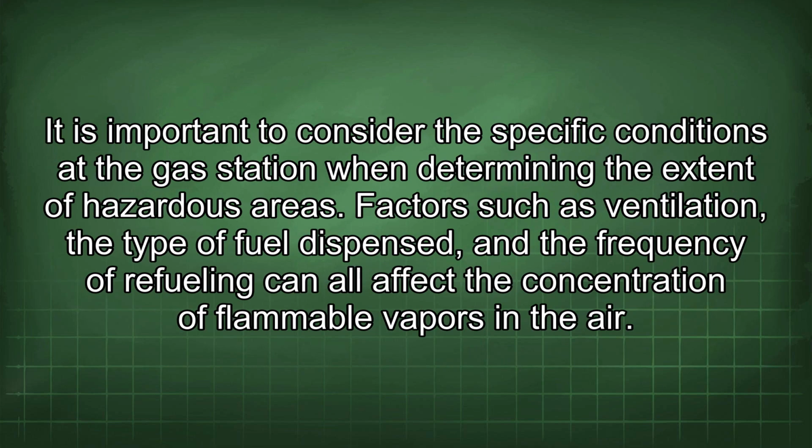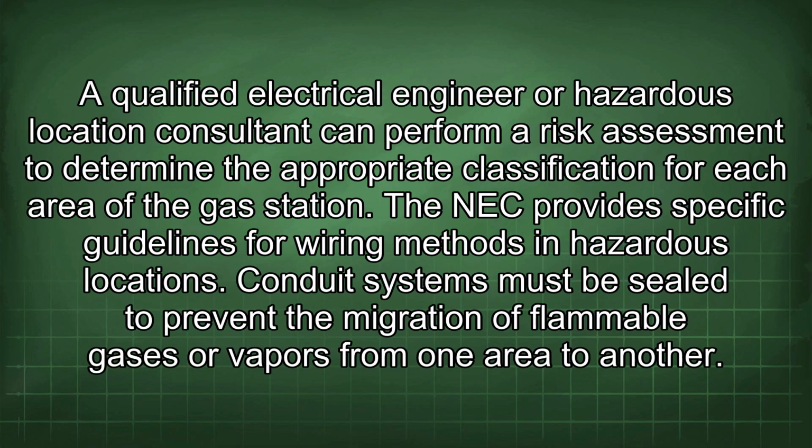It is important to consider the specific conditions at the gas station when determining the extent of hazardous areas. Factors such as ventilation, the type of fuel dispensed, and the frequency of refueling can all affect the concentration of flammable vapors in the air. A qualified electrical engineer or hazardous location consultant can perform a risk assessment to determine the appropriate classification for each area of the gas station.